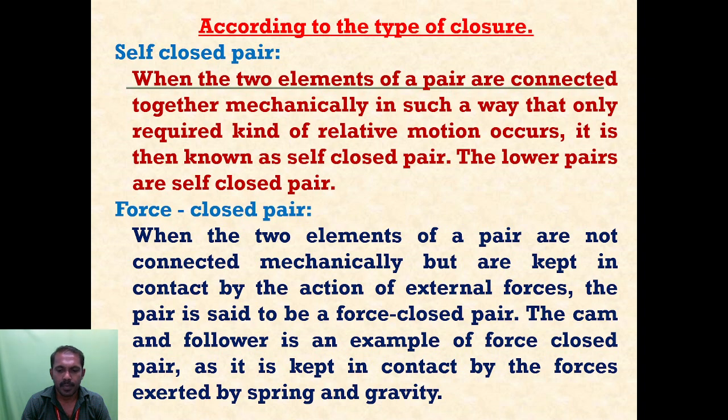Next, force-closed pair. When the two elements of the pair are not connected mechanically but are kept in contact by the action of an external force, it is called a force-closed pair. For example, the cam and follower is a good example of a force-closed pair.